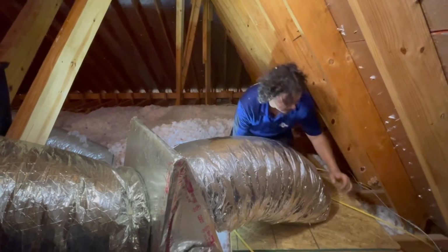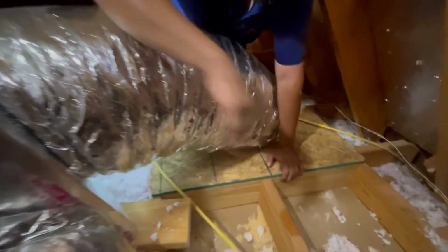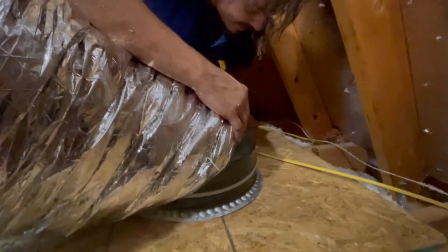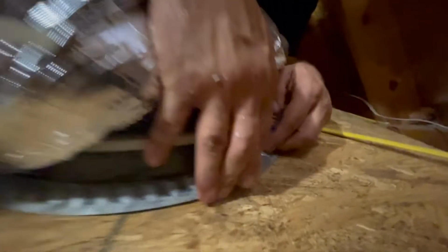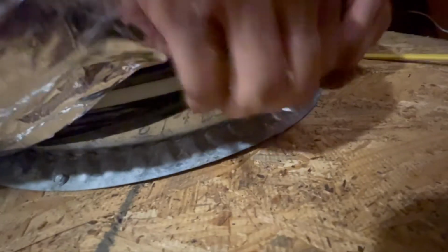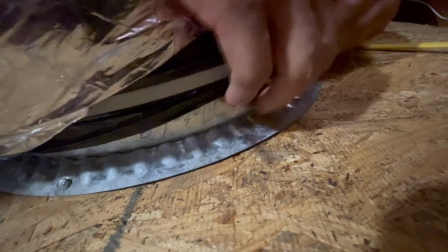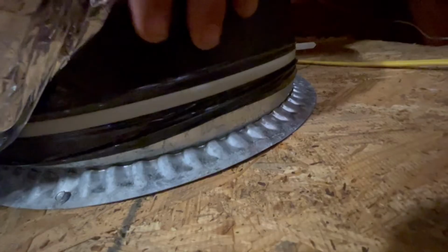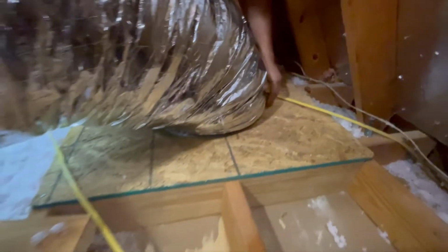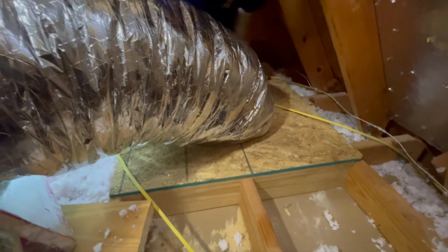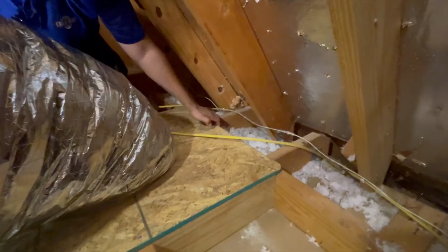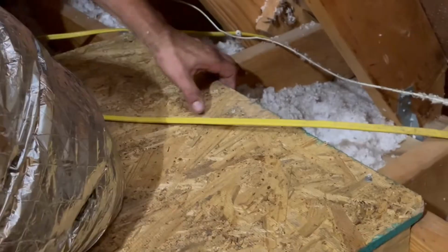So right here, obviously somebody's cut this in, added it after the fact. You can see that they did put a strap, however, there is no sealant applied anywhere. There's a lot of play in it. I would suspect that this is leaking. It's uninsulated. It's just a wooden box, no insulation. No attempt was made at air sealing. In fact, look here, I'm lifting it up all around the seams. Oh, let me get a close-up.